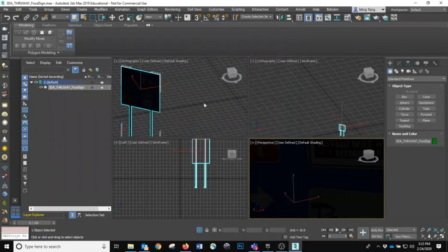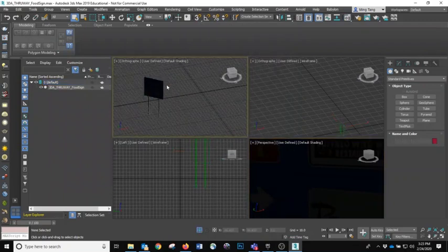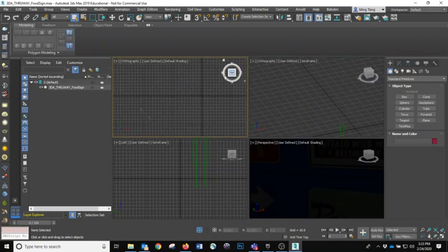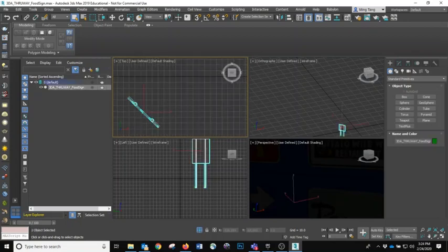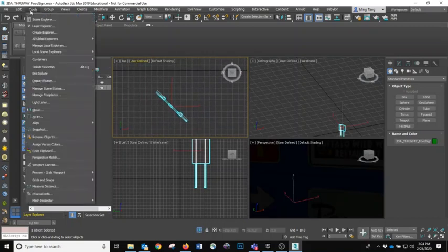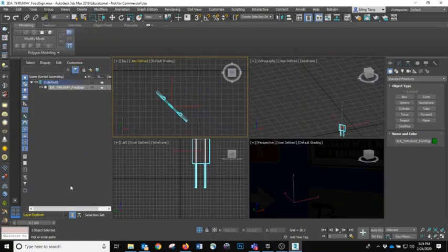Then we just need to export into InfraWorks. That's it. But before we do that, I think we should measure the scale, right? You want to make sure, also the orientation is kind of weird. Yeah, 45 degrees. So let's measure the distance first. If you go to Tools, measure the distance, here to here.